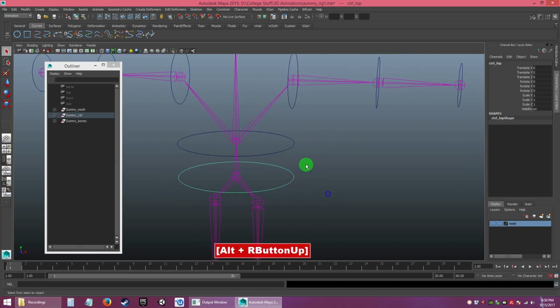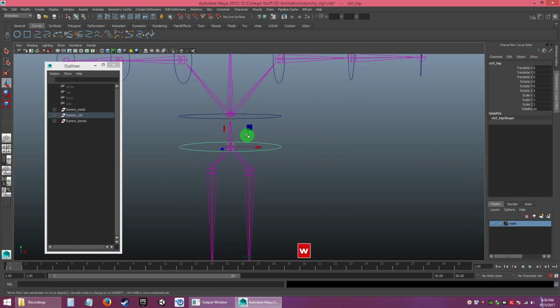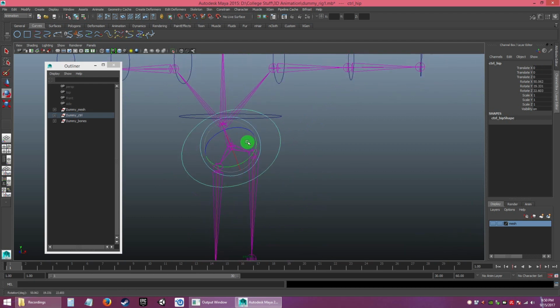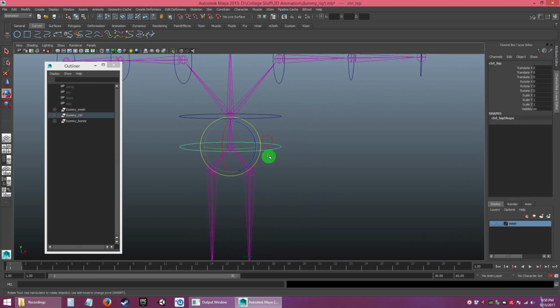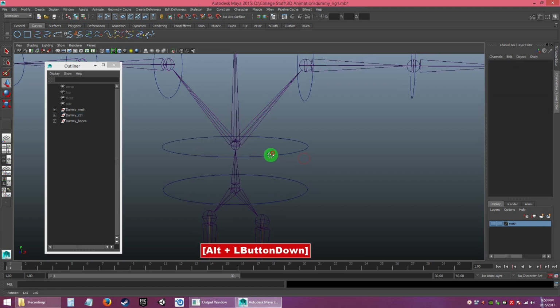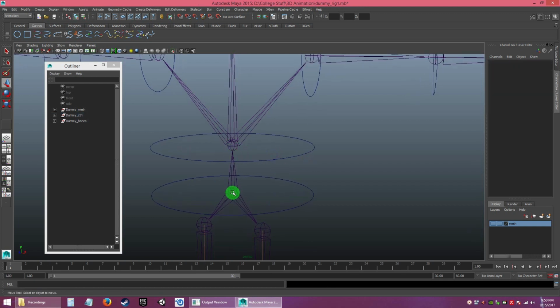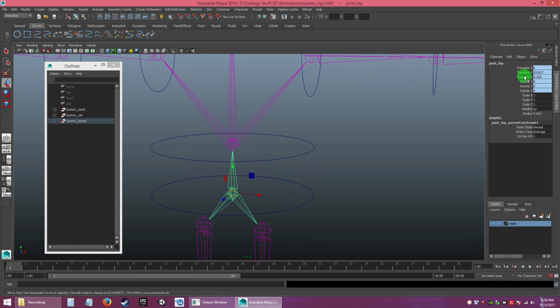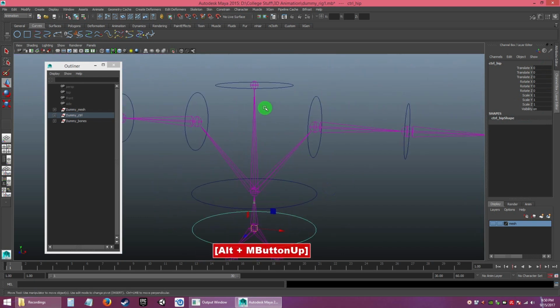But the hip is different, because our hip tends to move in space, and you also want the hip to be able to rotate. So that's why we use parent constraint for this. But the other parts here are just rotation. We are not going to be moving the bone because it's not logical. So reflect back on your bone anatomy. That's how it works, right? When you look at the hip here, you see translate and rotate is controlled by the controller here. Okay, let's continue on.